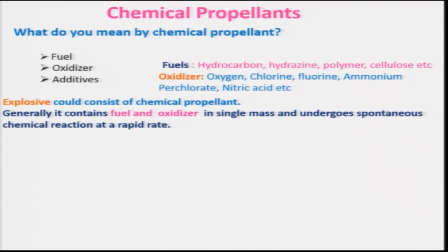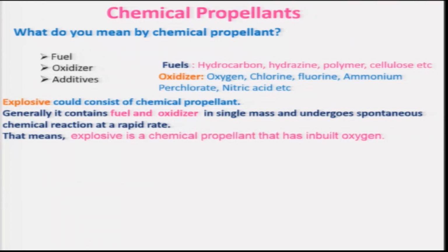It will be ignited and lead to a very spontaneous chemical reaction, occurring at a very rapid rate compared to general chemical propellants. So, in other words, an explosive is a chemical propellant that has inbuilt oxygen, as I told you, in a single component, sometimes mixed at the molecular level.